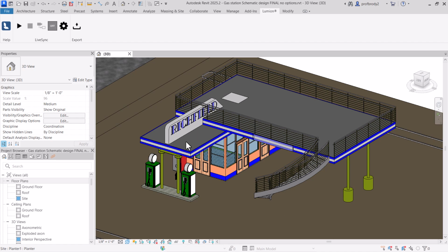The other instance where that happens has nothing to do with Revit, but if you have a photo, say a photo match from SketchUp, maybe you've loaded that into Lumion, sometimes those photo matches go haywire when you get into Lumion. Again, reapplying the material is the way to go, or applying a new material inside Lumion. Trying to fix it in Revit can actually be kind of a pain. And Lumion is where you want to do all of your final material settings anyway.